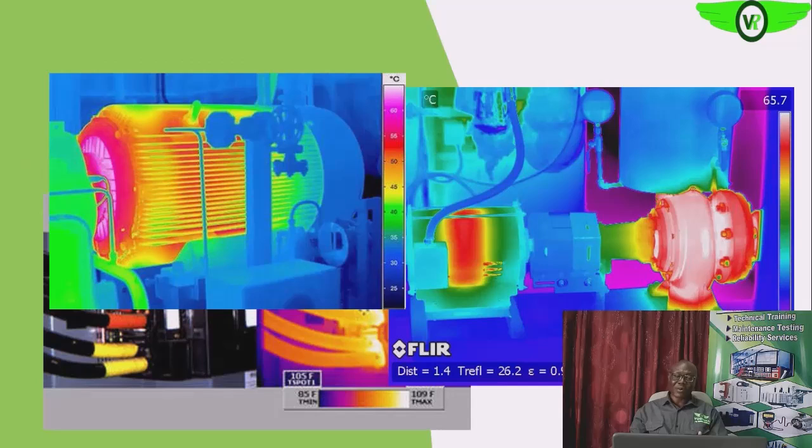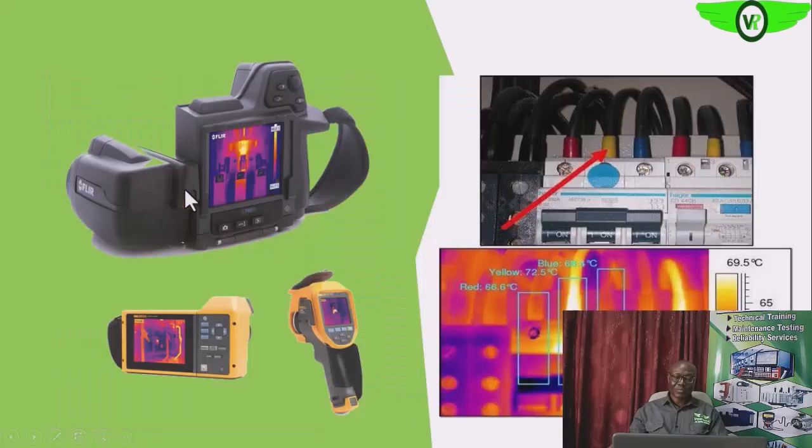We can also look at the pumps. You can see the driven load. It has its own normal thermogram, what we are used to seeing. If there are deviations, you also see them around the bearing housings. If there is a fault with the impellers, you also see these deviations. So this infrared thermography, in conjunction with other technology, will definitely give us what is happening around the electric motor. If you look here too, you see the normal thermogram of the electric motor itself.